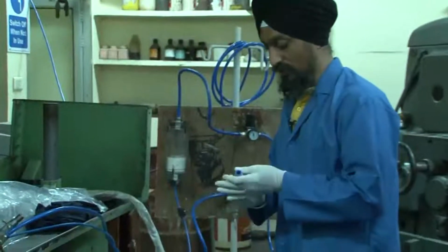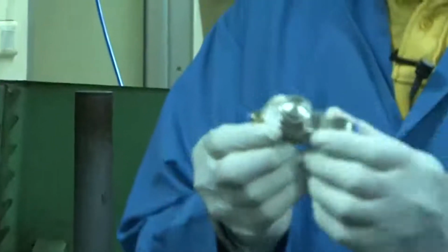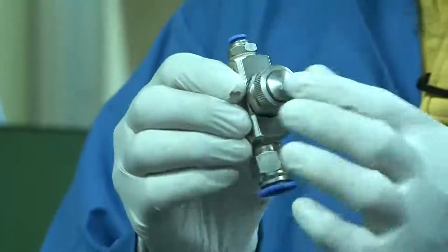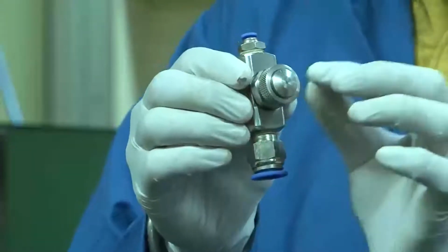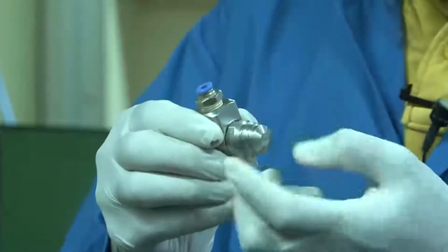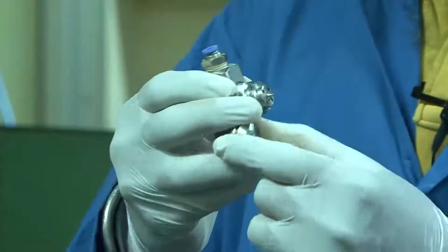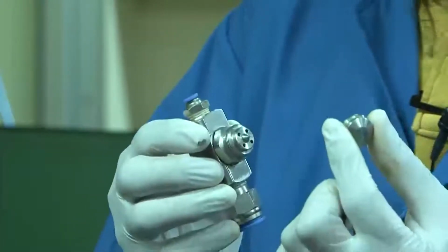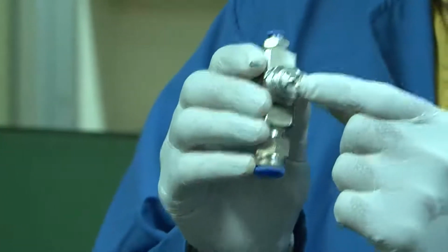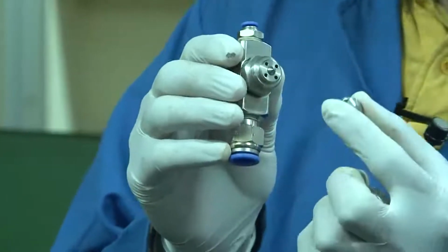We have already told you that this is a similar kind of nozzle. This nozzle has air and liquid inputs from the two ports, and we get a mixture, air atomizing here. This is our round cap, so the kind of spray we would have is round, as we already discussed. We also have flat caps and some other types. These are the 4 holes from which air would be coming, and there is an orifice from which liquid will be coming. So this is an external mixing kind of nozzle.